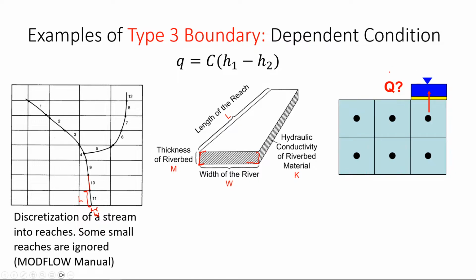So let's look at it here. You overlap your river over your aquifer. So this is like a bird view. This would be like a cross-sectional view. And let's say the head in my river is here. That's the head in the river. And let's say the head in my aquifer is much lower. Like this is the head in the aquifer. And if the head here is higher than the head here, I'm showing that water will flow from here to here.